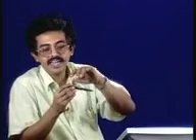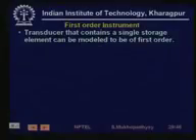So even if you suddenly fill this space with, let us say, steam, the temperature of the junction of the thermocouple will not instantaneously be equal to the temperature of the steam, but it will slowly rise, right? For such transducers, we have a first order instrument character, first order or second order. That will depend on the modeling of the thermocouple.